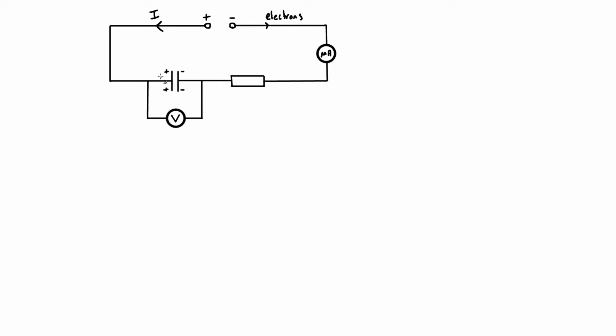the capacitor. Initially, when the capacitor is uncharged, there will be no volts across the capacitor. The reading on the voltmeter will be 0, and all of the volts from the power supply will be across the resistor here, driving a current through that resistor. Because the capacitor and the resistor are in series, the potential difference across the capacitor plus the potential difference across the resistor must add up to the terminal PD of the power supply.